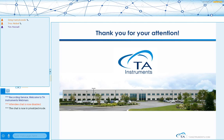Okay, I'm going to do one last question, and then we'll do the rest via email. You talked about this a little bit, but maybe just to revisit real quick, how to correlate on gelation tests the rheometer results as a function of time. How do you correlate those to the practical gel point in a cross-linked material? Well, generally, what we see is that when you go beyond the gel point and the G prime is now higher than the G double prime, right around that point and a little bit afterwards,